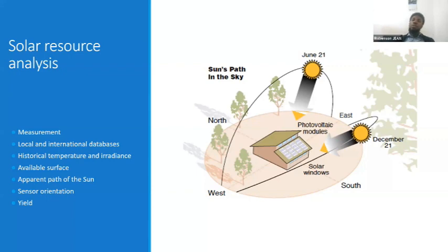At that moment, we have only a component of the direct radiation, not the total direct radiation. So in order to harness the total direct radiation, we have to put our module in such a way that the direct radiation arrives perpendicularly to the plane of the module.